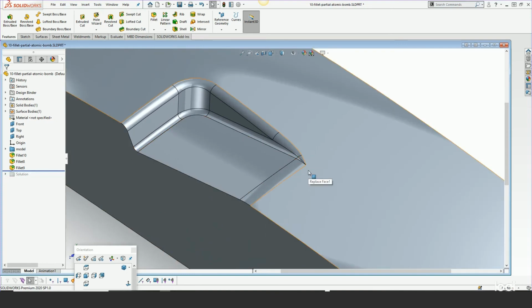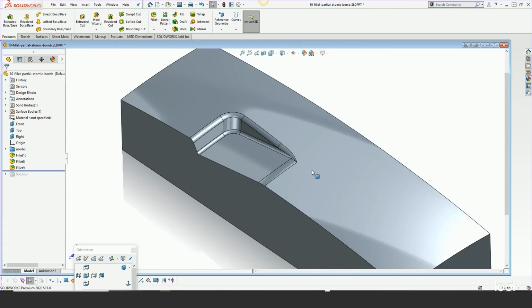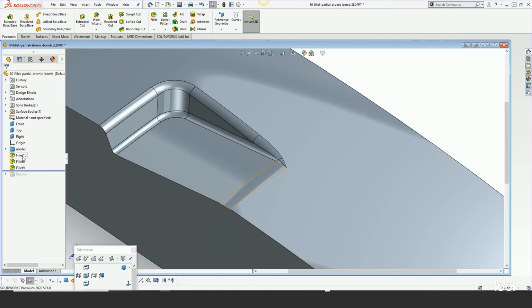technique, which I remember now, I think came from Keith Peterson many years back at a SolidWorks World when he presented it. Fortunately though, with a new feature that came in SolidWorks 2019, we no longer have to use that method. And I think using the fillet partial edge option is going to make fillet solutions like this more robust. And let me show you what I mean.